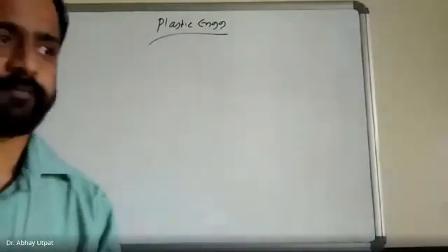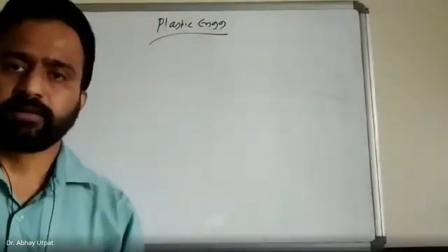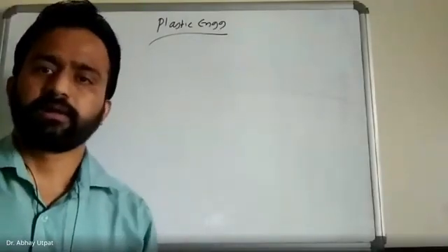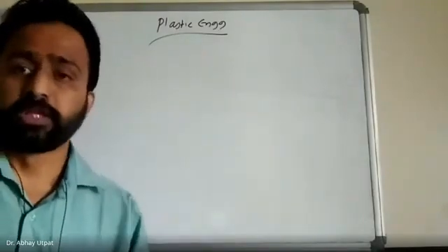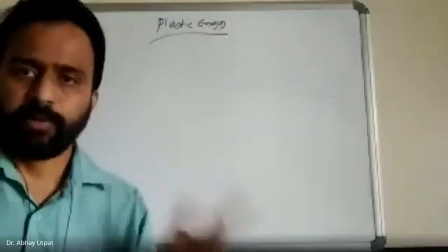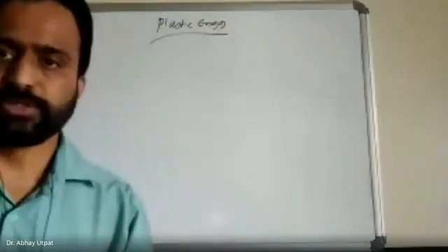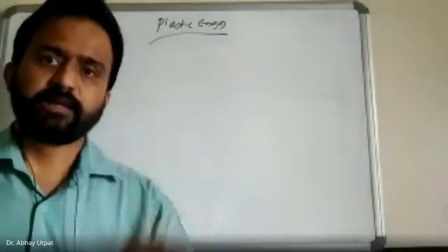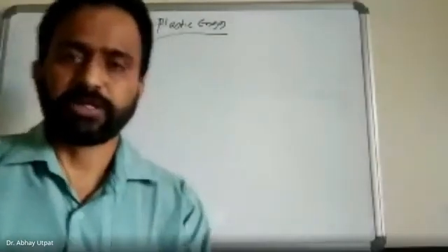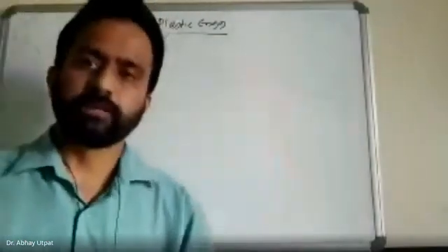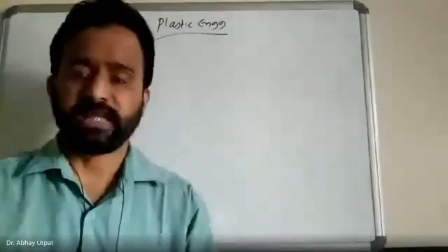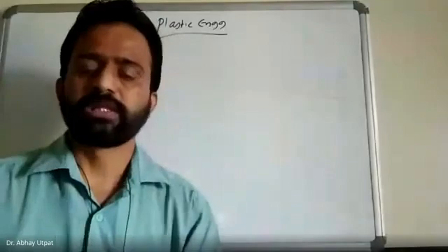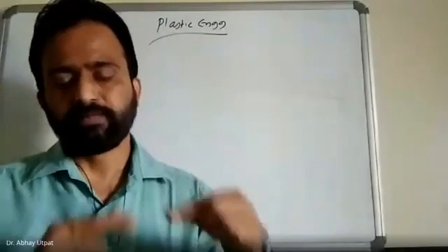So in thermoplastic, what we have seen, thermoplastics are the plastics which are recoverable, which you can reuse, recyclable, whereas thermosets can't be recyclable. Heat makes them soft, thermoplast. Heat makes them set and hard, thermoset. So once you use the thermosets, it can't be recycled. So that is the advantage and disadvantage. Then thermosets have cross-linked polymers. Thermoplasts have single chain type polymer.